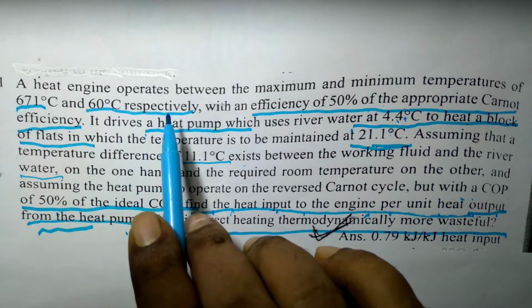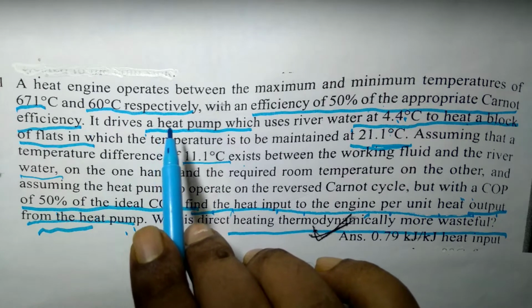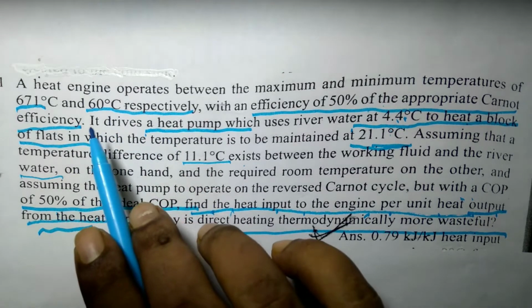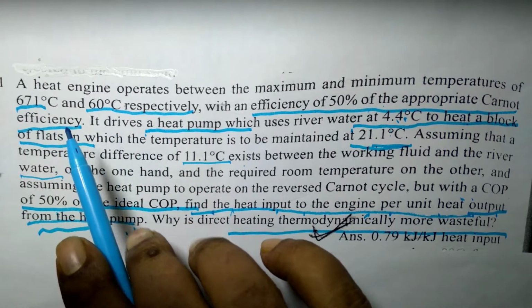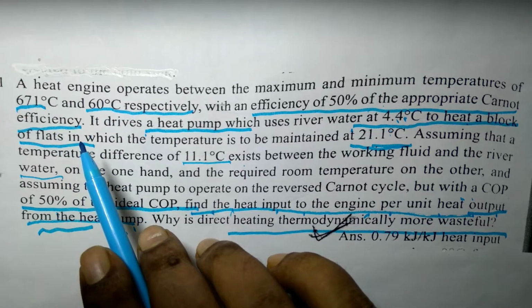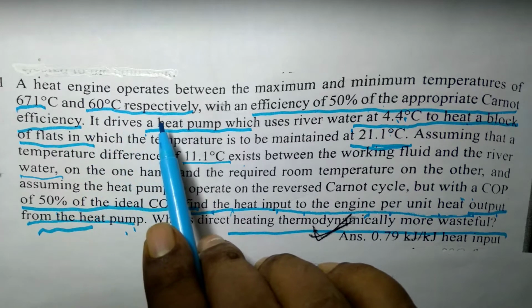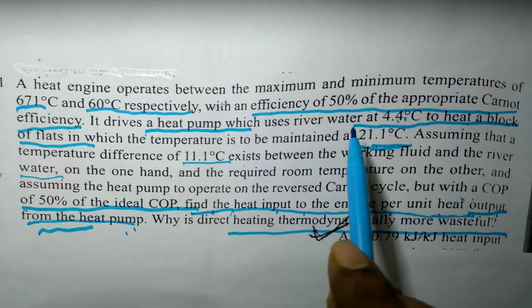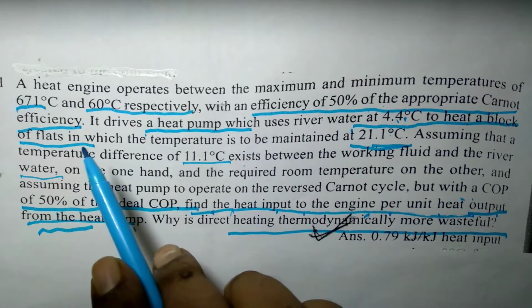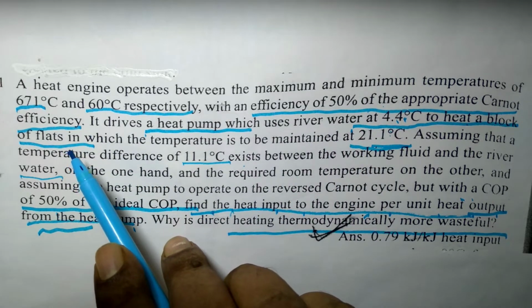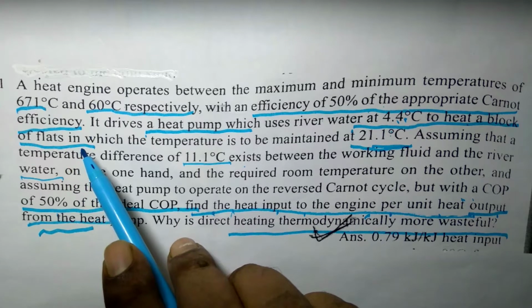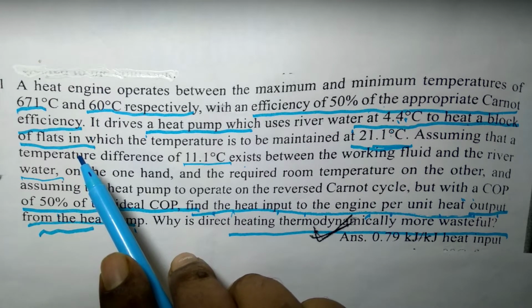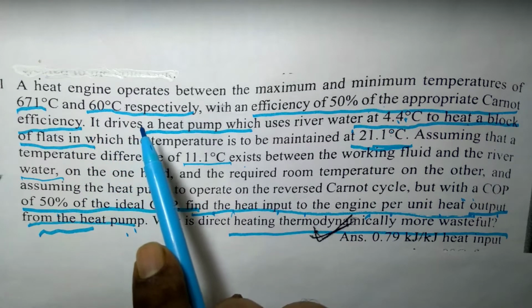The given heat engine operates between the two temperature limits, 671 degrees Celsius and 60 degrees Celsius, with an efficiency of 50% of the appropriate Carnot efficiency. Carnot efficiency we can easily calculate as 1 minus TL upon TH,